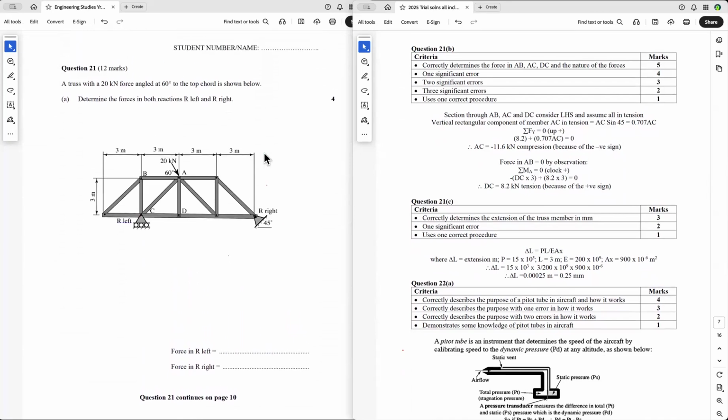So when you have a look at it, AB has got no external forces on it. And so all these members here are redundant members as it's loaded here. So that's got no force in, that's got no force in, that's got no force in. But whenever you see a member joining a chord, that force there is zero in that.